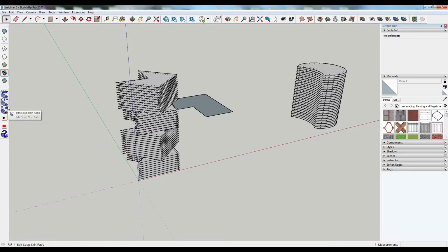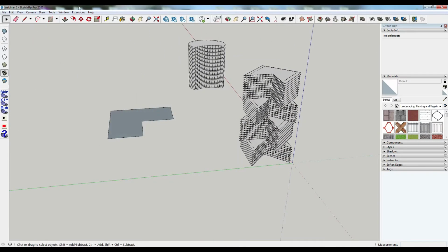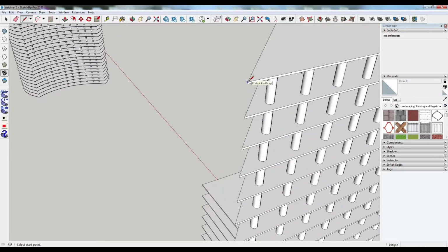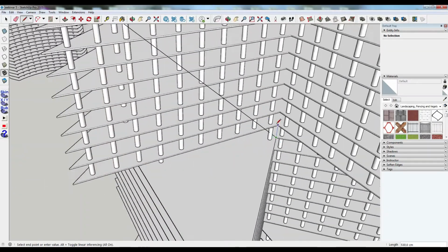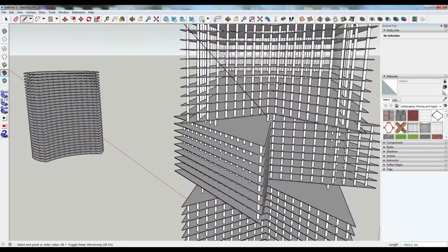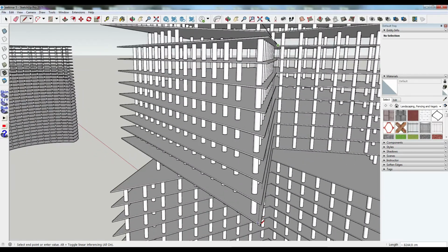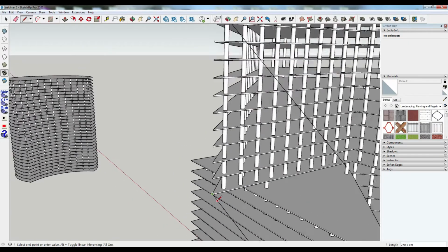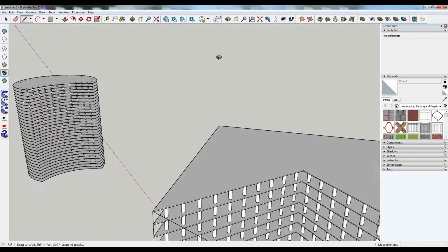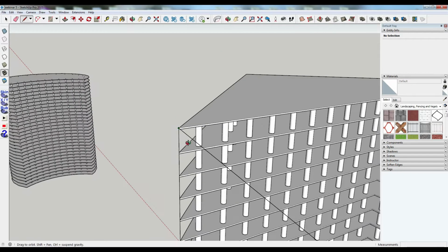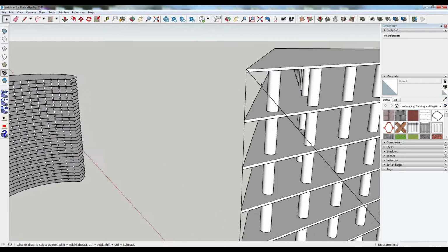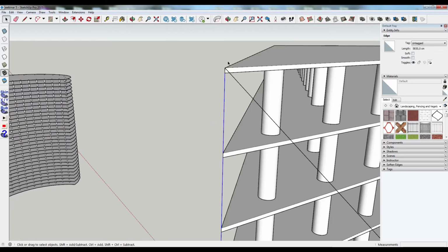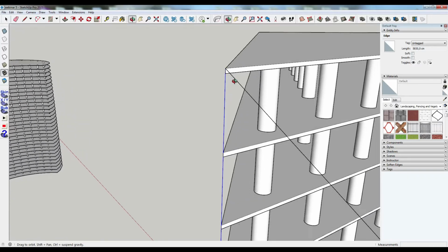It's the time to benefit from the bubble skin extension. To work with it, we will click on line tool and we have to make a closed surface first. It could be made of different geometry elements, arcs, complex polygons, it doesn't depend, but it's very important to be all closed. All the elements should be touching in a contact point.